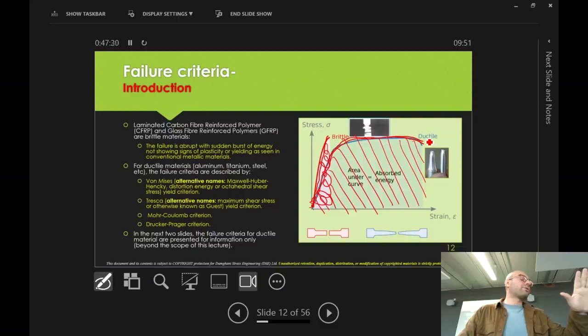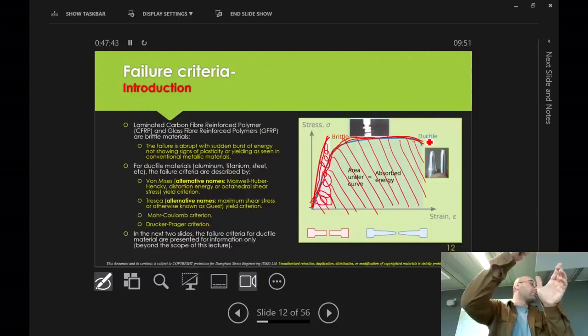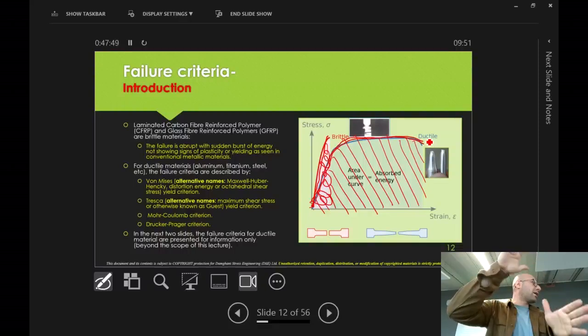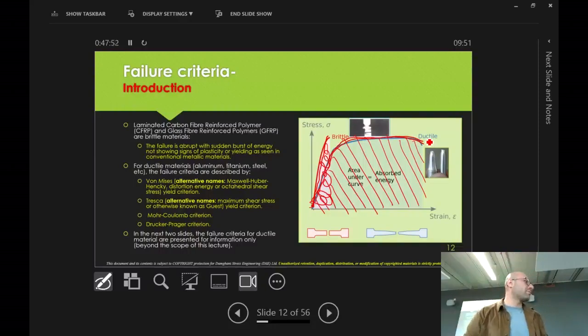And because the operating temperature of an aircraft is, let's say, minus 20 degrees sometimes, some people say minus 50 to 85 degrees Celsius, they've created, at the interface of them, slotted holes so that when one expands, there's a space allowed for that expansion so that residual stresses do not take place. Lots to consider, but you're right.